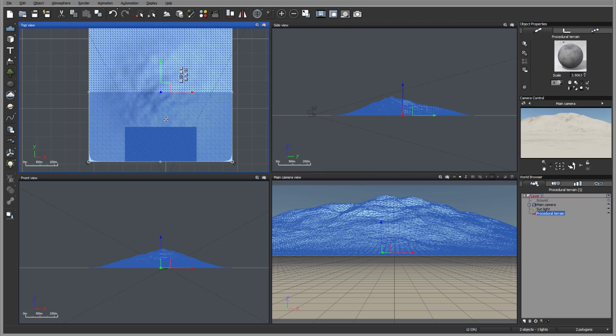And of course, if we take the camera and move closer to our scenery, it will increase details to infinity because it's using fractal functions. And the closer you get, the more details it can produce. That is very nice if you're creating close-ups or you don't know the position for your camera. However, it does take additional CPU time when you render to set proper resolution. And another drawback with this: even though it holds its shape, if you move the camera closer it needs to render those details. So it means the shape may change in very insignificant ways, but it will re-render.